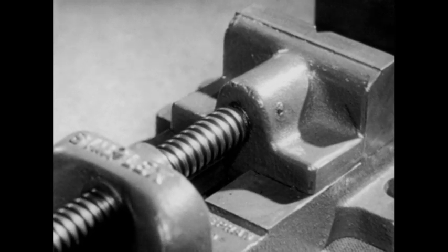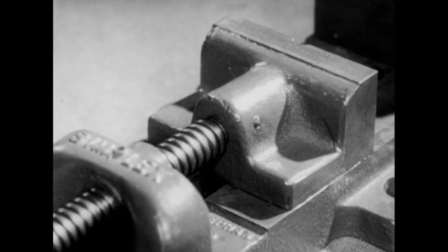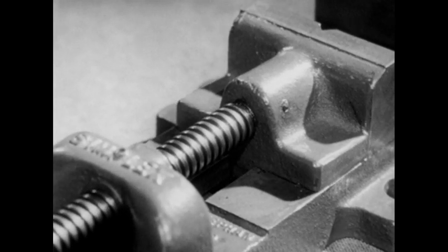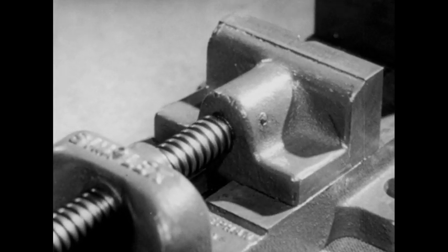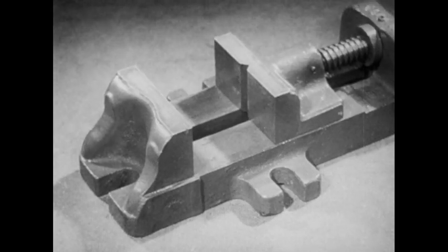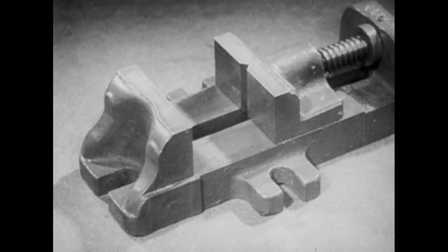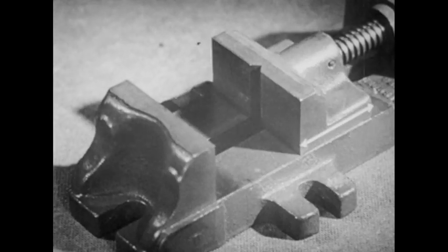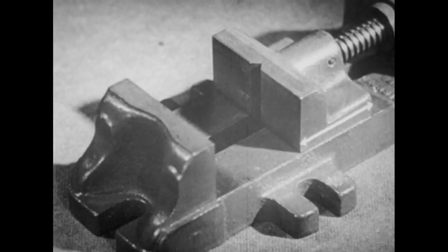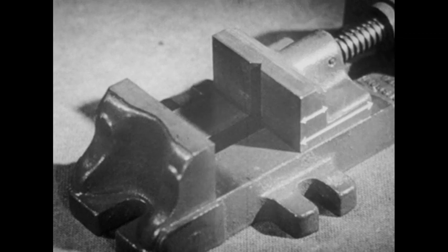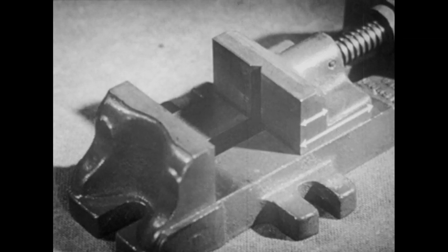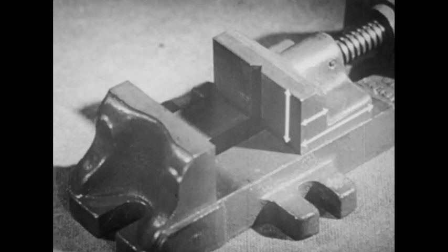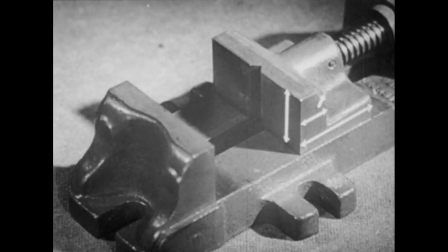So far, all the dimensions you have considered are important to the functioning of parts of the drill press vise. Other dimensions have only strength requirements. Consider the pattern maker primarily in giving these dimensions. He will need the length of the movable jaw, the thickness of the jaw face, and the height of the jaw face to the unfinished surface. Specify the radius of the back of the jaw.